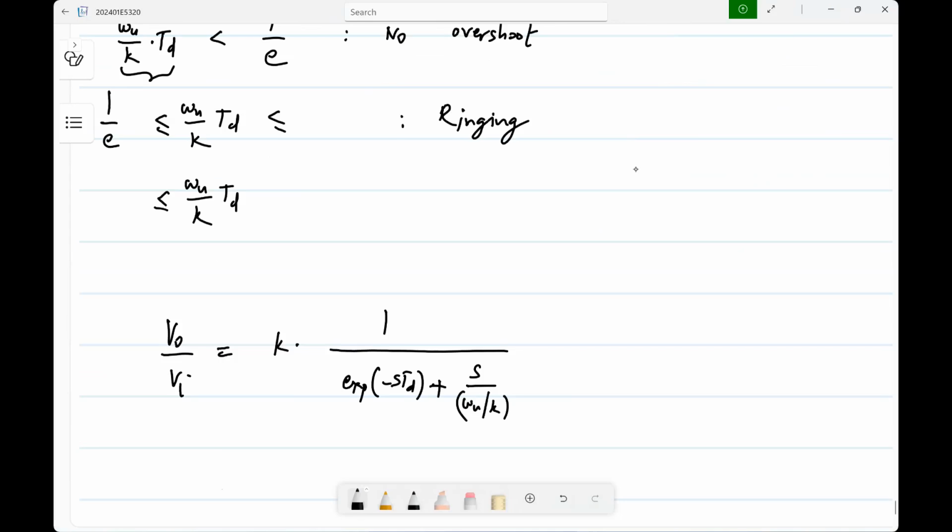If I have a transfer function, you look at the denominator. Then what were the natural modes of the system? Yeah, so you find the roots of the denominator polynomial. So natural mode means exponential of that root times t. That is the natural mode. Okay. So the actual natural response will be some linear combination of these natural modes.